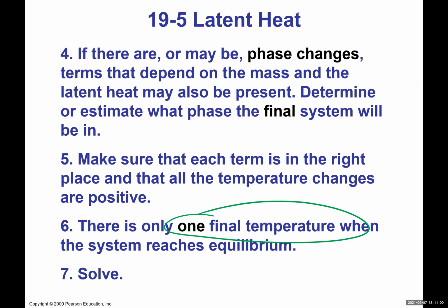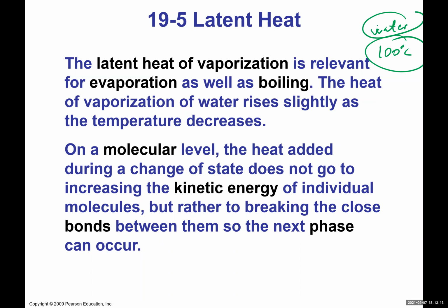The heat of vaporization of water rises slightly as the temperature decreases. On a molecular level, the heat added during change of state, or change of phase, same thing, does not go to increasing the kinetic energy of individual molecules. That's why the temperature doesn't change, but rather to breaking the close bonds between them so that the next phase can occur. Okay, so you can think of it like this. For the ice cube, right? You have a solid, an ice cube. Those are the molecules, and they are all bound to one another with sort of like, let's say, spring-like forces.